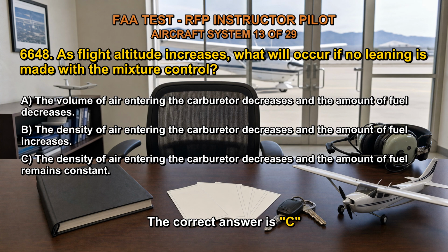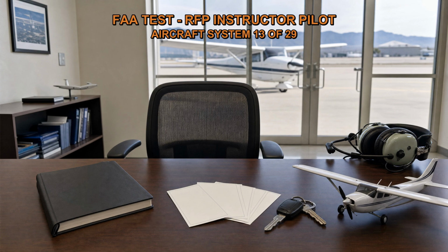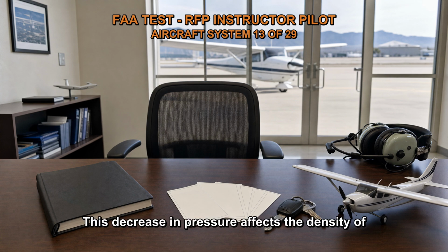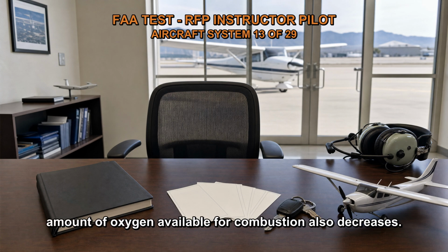The correct answer is C. When an aircraft climbs to higher altitudes, the atmospheric pressure decreases. This decrease in pressure affects the density of the air, which refers to the mass of air per unit volume. As the density of the air decreases, the amount of oxygen available for combustion also decreases.